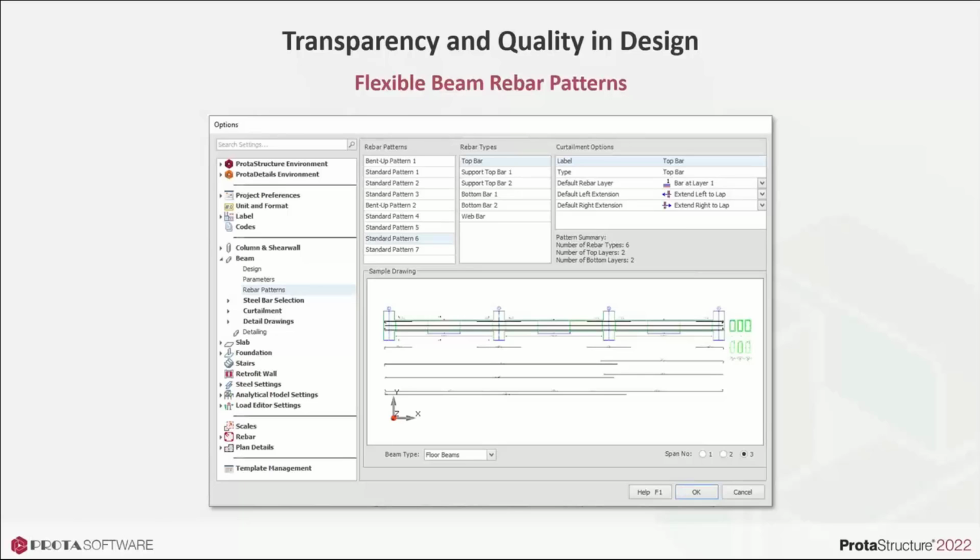That's actually a huge improvement over the beam design functionality in previous versions. So in short, with these patterns, you can now introduce as many layers of bars as needed in your reinforced concrete beams.